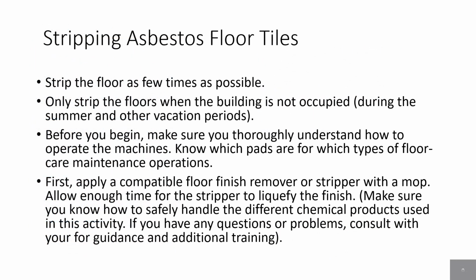Stripping asbestos floor tiles. Strip the floor as few times as possible. Only strip the floors when the building is not occupied during the summer and other vacation periods. Before you begin, make sure you thoroughly understand how to operate the machines. Know which pads are for which types of floor care maintenance operations.